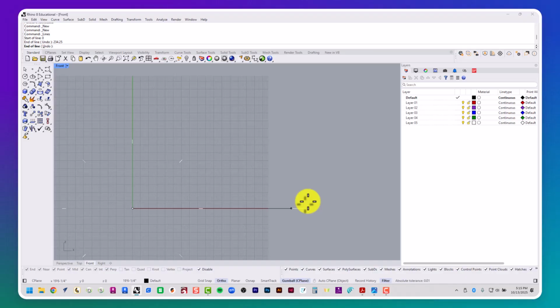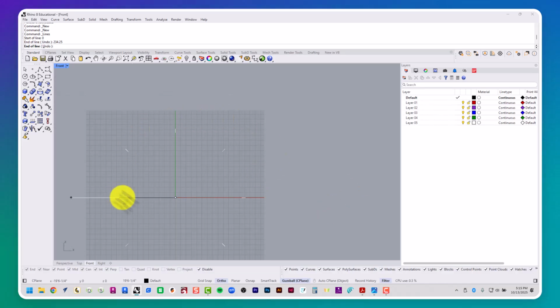As you can see down below, it says 19 foot 6 1/4 right here. So things are being displayed in feet and inches. Now that I've made a line that's 234.25 inches, the next thing Rhino is asking me is, which way does this go? And once we're going in the right direction, please click. If I want it to go this way, 234 inches this way or this way, I want it to go this way. So I'm going to click once.